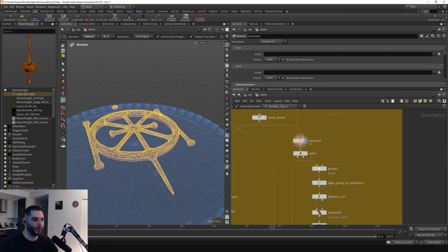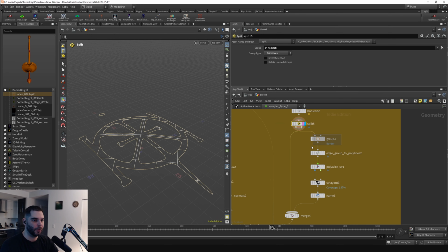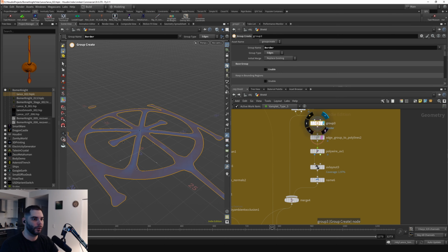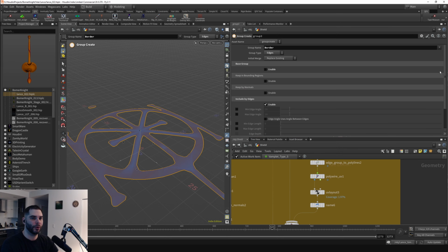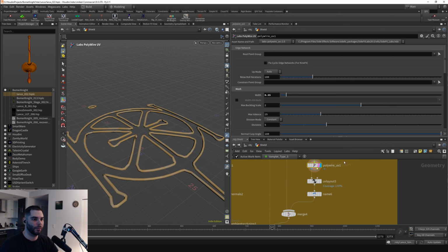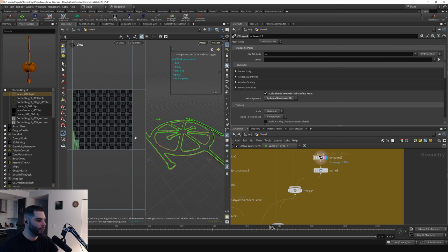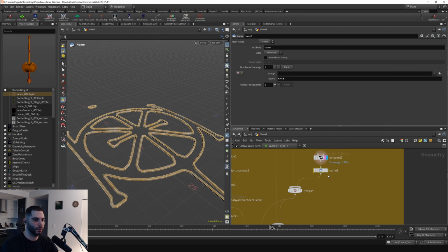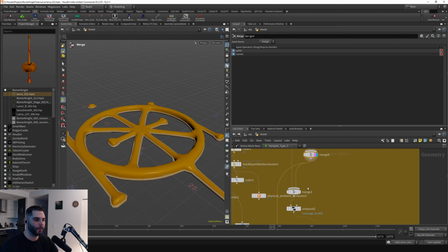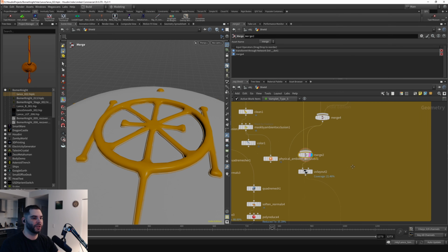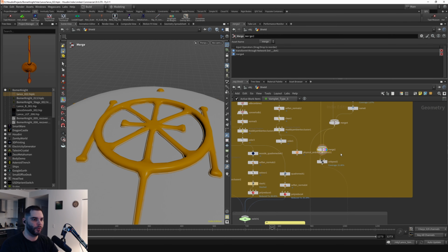using the shield. I booleaned it and split the bottom, and I guess I used that bottom piece to do a poly wire. Grabbed the edge border using this, and then took that group and did a poly wire, and then the UVs are laid out. Named it trim group. Now we have a bit of a trim around that, but this was a different version of the shield.